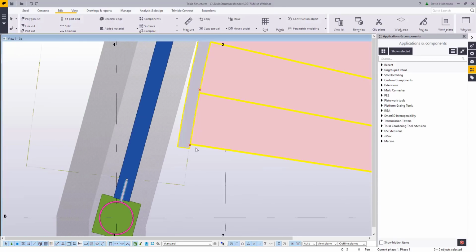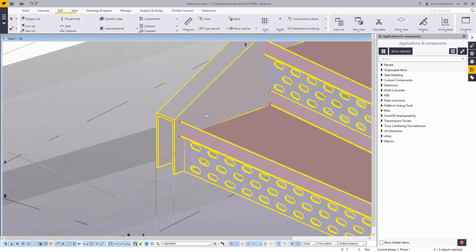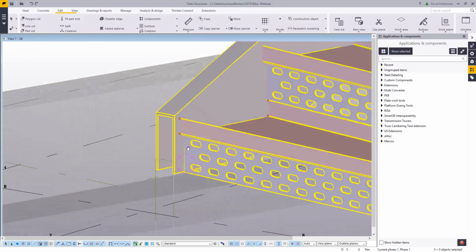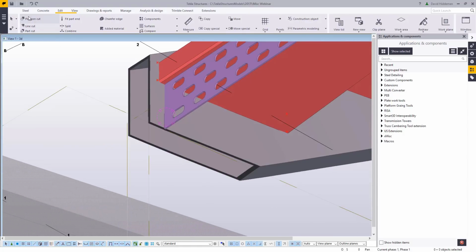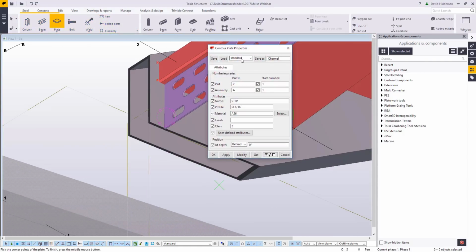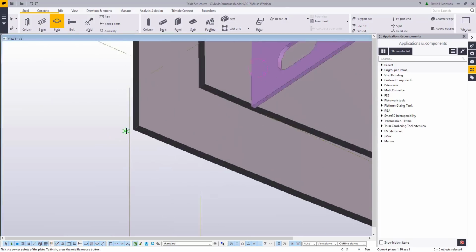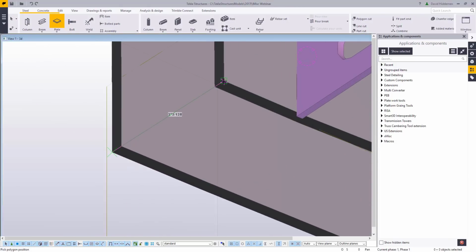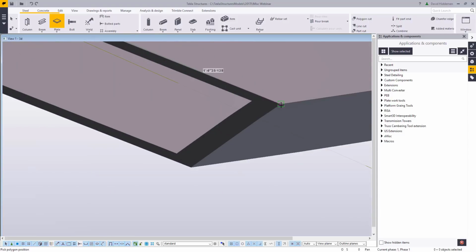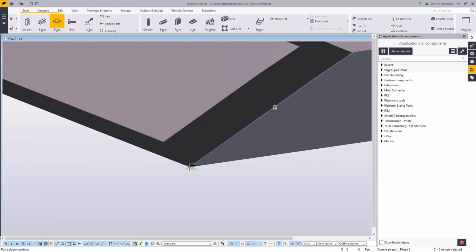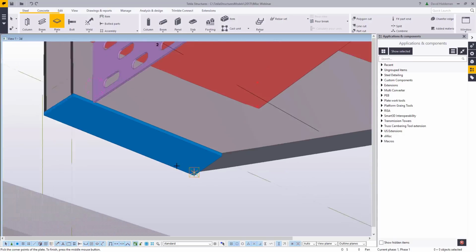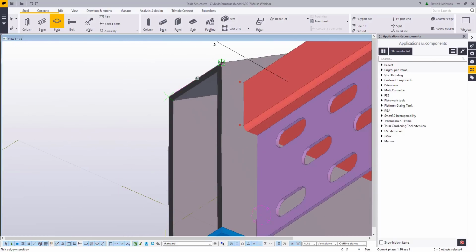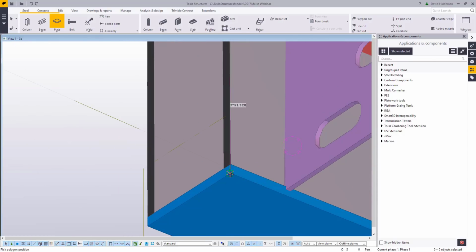So that quickly I've been able to create the cuts to shape the bottom of that stringer the way I want. And then we can use the plate tool and just draw in our closure plates. So I'm going to make this 1/4 inch thick. We will just pick, connect the dots coming around that cut end of the HSS. And then I'll do the same thing for the very end of it.